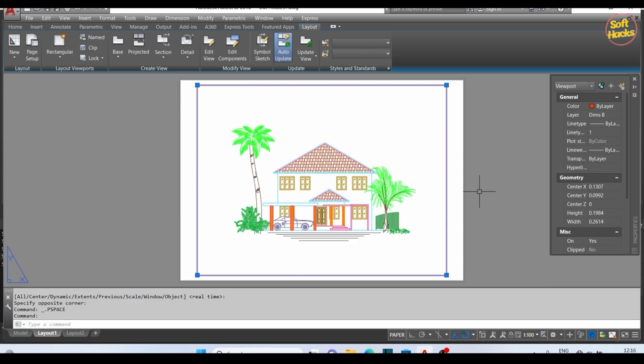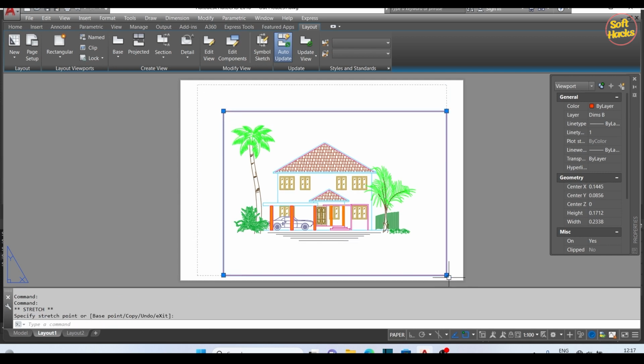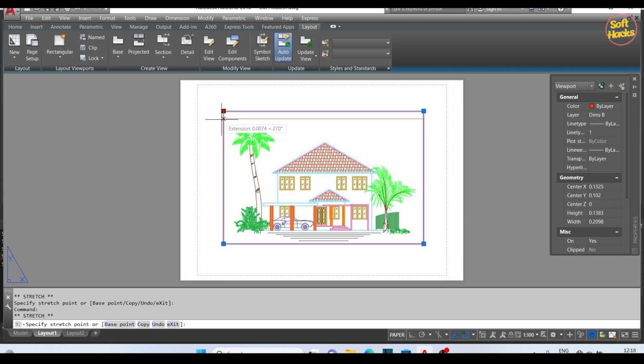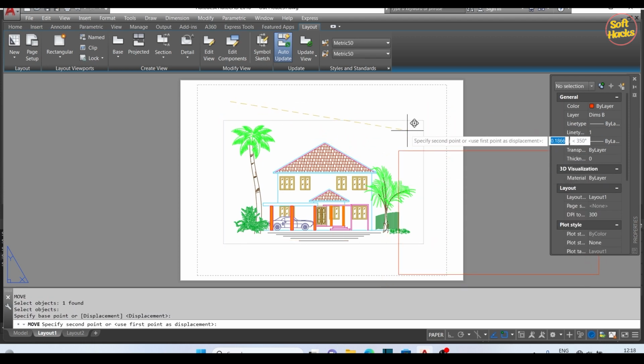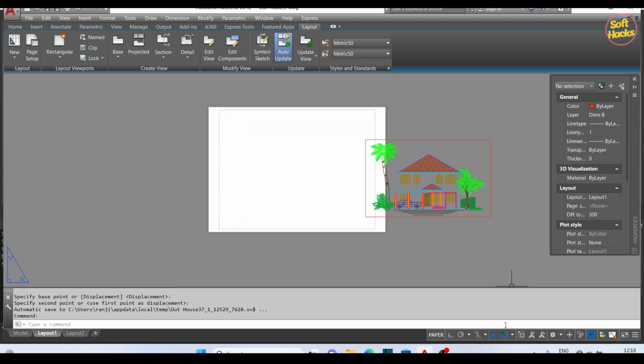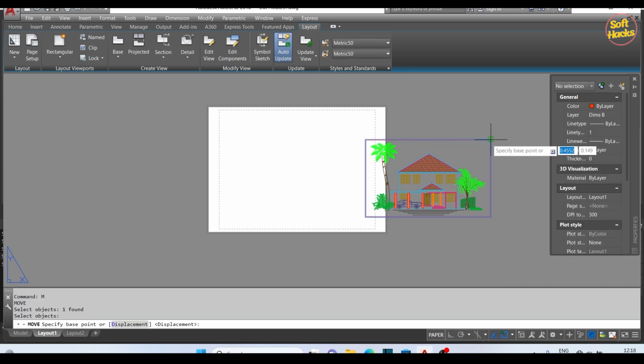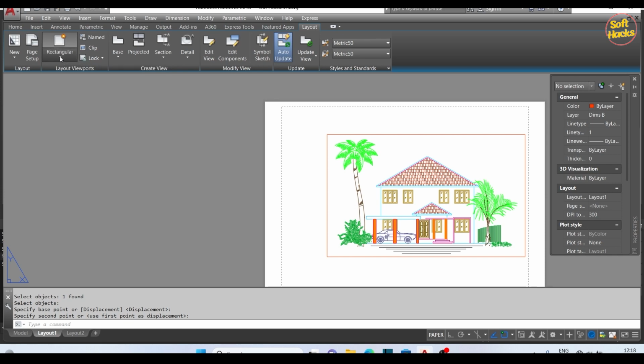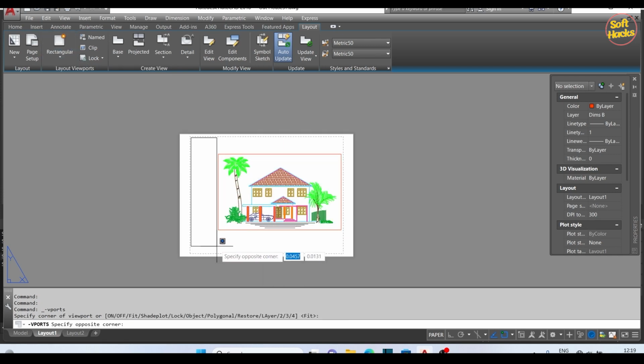And you see here now the drawing has no title box, but there was one. If you want to bring it back, you can easily do it by inserting another viewport. For that, I'm going to stretch it. I hold this grip and resize it to a comfortable size. This operation will not disturb your set scale. With the move command, you can move the viewport anywhere you like without losing its contents or disturbing its scale. Then I move the entire viewport to a suitable position. I click on this rectangle viewport to create one, and it's here.